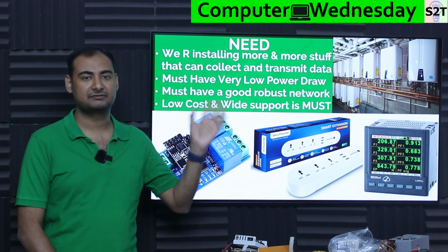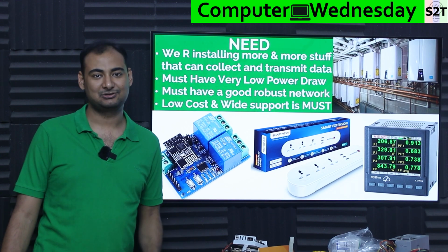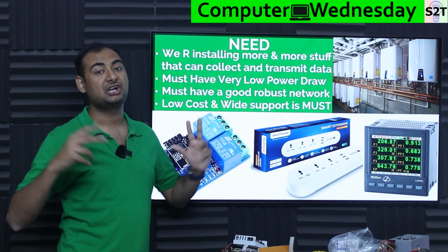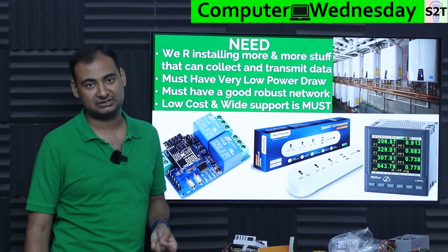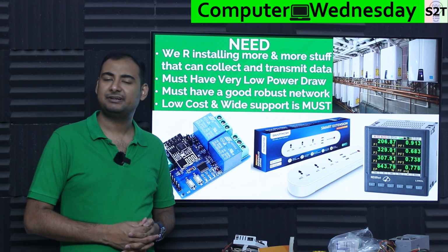Now imagine if you put a lot of sensors and each sensor is consuming too much power to communicate data, the power draw of the building will go up. So fundamentally it has to be very low power, because we are expecting to put hundreds of these puppies. So: low power draw, wireless, and it must have good network robustness, because once you start to amplify the numbers, you have to realize very early on that Wi-Fi is not designed for that.